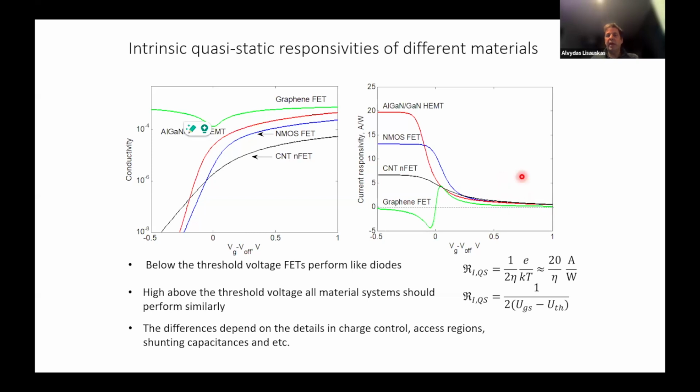So on one side, graphene FET has those access regions, which were working as a parasitic element here, but due to very nice energy transport, was not described by Dyakonov. Actually, they can operate even at frequencies much higher than terahertz, where other phenomena lose. So the plasma wave that I discussed here starts to lose with the frequency, but other phenomena are coming in. So in general, for an engineer it makes not much difference; it depends only on knowing more about the parameters and the technology you apply to make decent sensors, doesn't matter which technology it is.